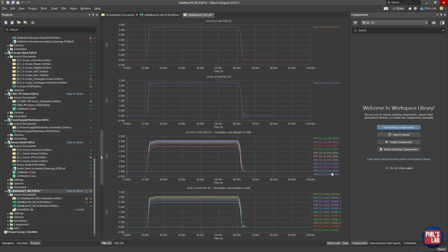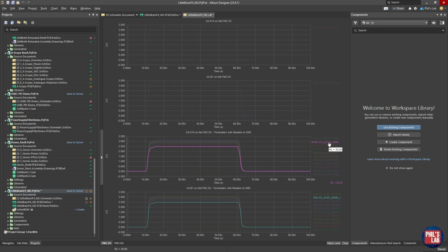For example, if we select one of these waveforms, the waveform with a termination resistor of 180 ohms, we can see we've already substantially decreased the ringing and overshoot, but we do have some undershoot still. With the termination resistor closest to my trace impedance, which is 50 ohms in this case, we can see there's quite a significant DC drop because this simplified model of the driver doesn't have the current requirements to drive this heavy load, this 50 ohms at DC.